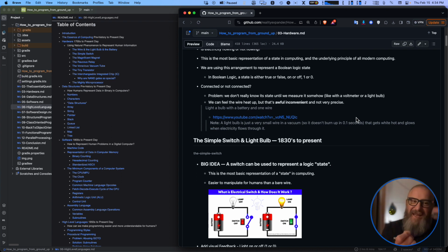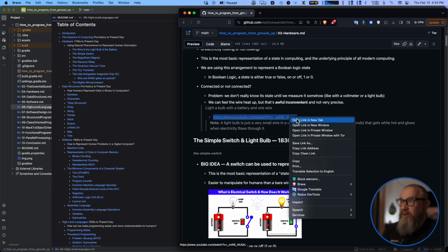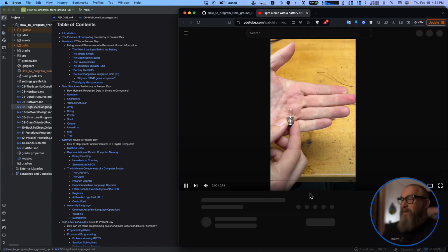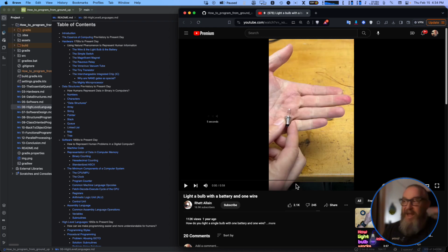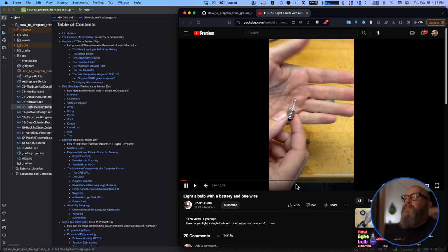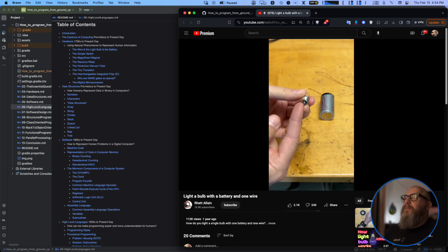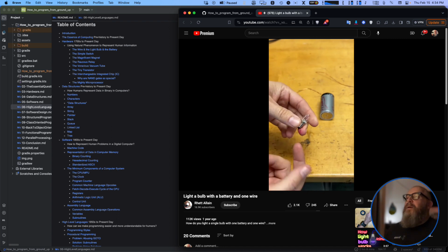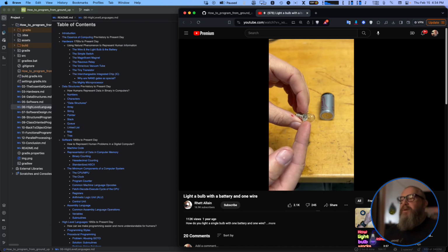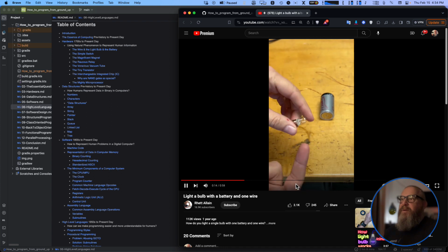That was probably the origins. When they were heating these wires, they would glow white hot. And that's basically what a light bulb is. It's just a little wire inside a vacuum. To make a bulb like this light up, you need to have current glowing white hot and not burning. That's why the vacuum's there, because there's no oxygen, so it doesn't burn. So that's why it can glow for so long. You need to have current coming into the nub part right there and then coming out of the side, or it doesn't matter, it goes either way. It's connected and that makes this filament with electric current get really hot and glow. That's how these incandescent bulbs work.